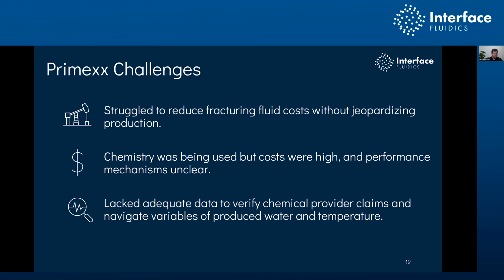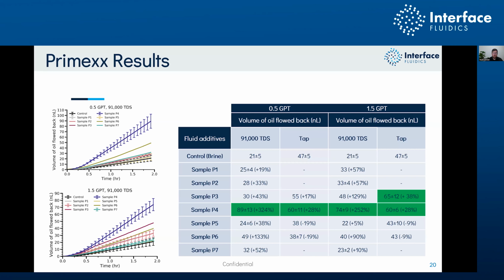And so the goal of this project was to understand: is the surfactant doing what we thought it was doing? And are the manufacturer recommended loadings the appropriate loadings for our well at our time? I'll walk you through all the numbers and data on this slide. But the ultimate finding was that switching surfactant providers and changing the loading of that surfactant resulted in higher performance. So I'll walk you through how we get to that conclusion here.